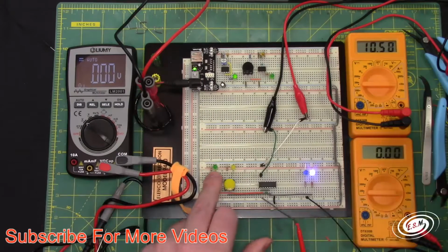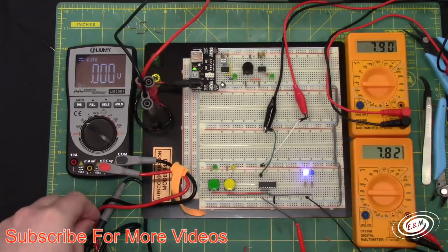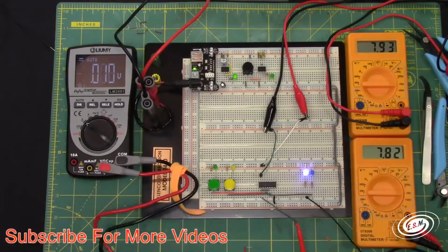So if I set it, it drew 10 milliamps there for a second. I could put this on the scope to see the curve, but 7.9, and with this LED it's about 8.08 milliamps difference. And it could be a different forward voltage on these LEDs.